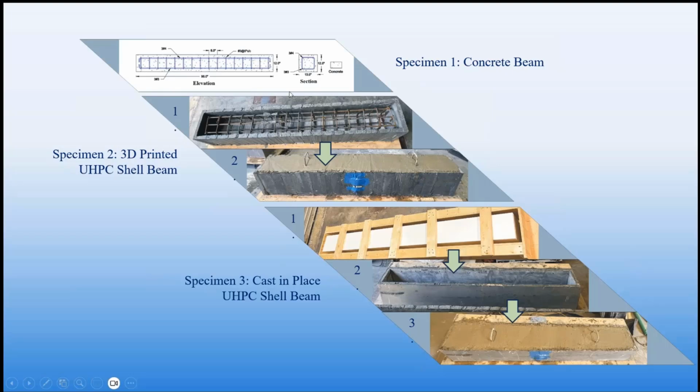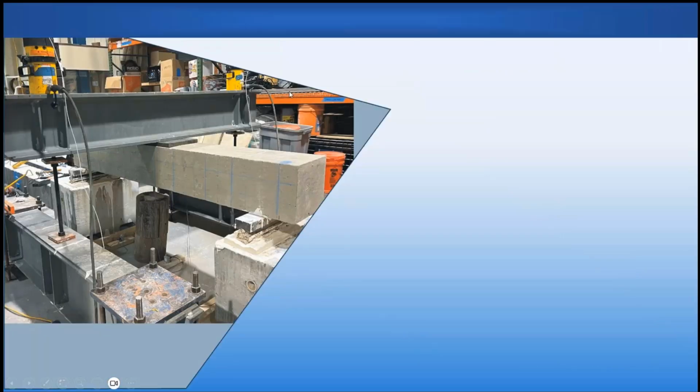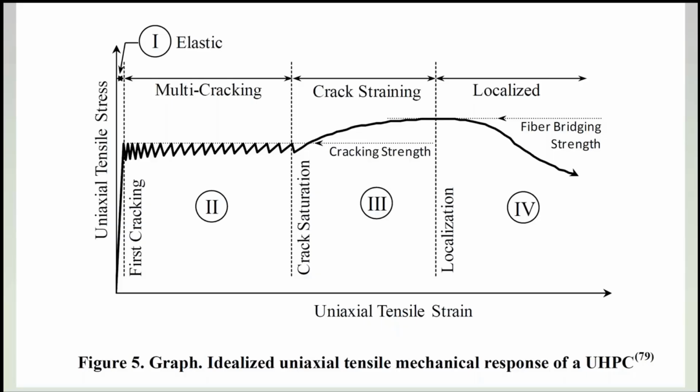Now, one thing you can find, especially in a flexure tension zone with UHPC, let's say you have a beam subjected to flexural loading moment, you get distributed cracking.